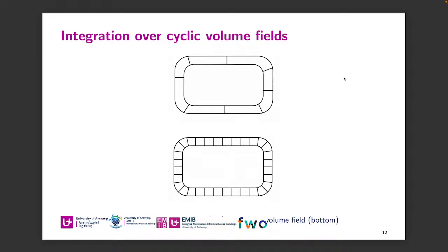What we do is very simple: we shift the water through this field and then we mix the volumes back into those fixed volumes where they end up. But that is a very costly operation each time step, because you need to calculate for each volume how much of it ends up in which volume, and doing that every time step for a different mass flow becomes very costly.